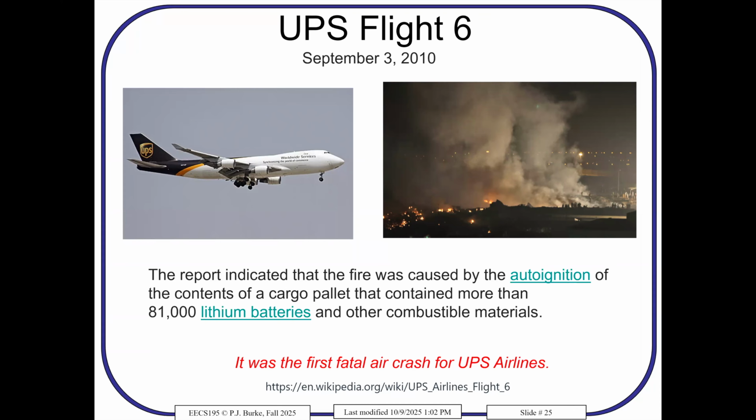The honest answer is if you crash the drone in the drone cage and there's a LiPo fire and the fire department comes, I don't think there will be anything burning more than the battery. But once a fire starts, it's better to have the fire department make that decision, not you. In the lab, if it happens, just pull the fire alarm and get everyone out. If you pull the fire alarm, that'll also trigger the fire department to come. Yes. That's a good idea. I should ask for that.